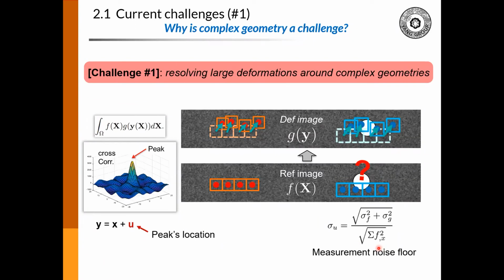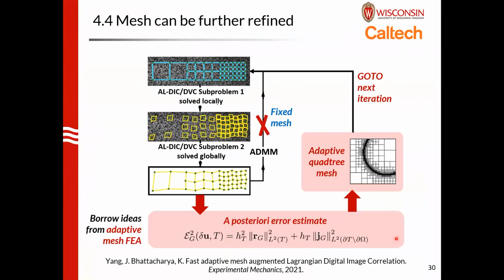Okay. And what if you cannot generate those binary mask files, because your discontinuity is so small? It is there, but it's so small you cannot have a binary mask file before the tracking. There is something I didn't include today. I have one comment here: the mesh can be further refined. You can always compute error estimates and further refine the mesh. So even if some of those discontinuities are so small that you cannot use Fiji or other software to measure them, based on these error estimates you can still update and refine the mesh.